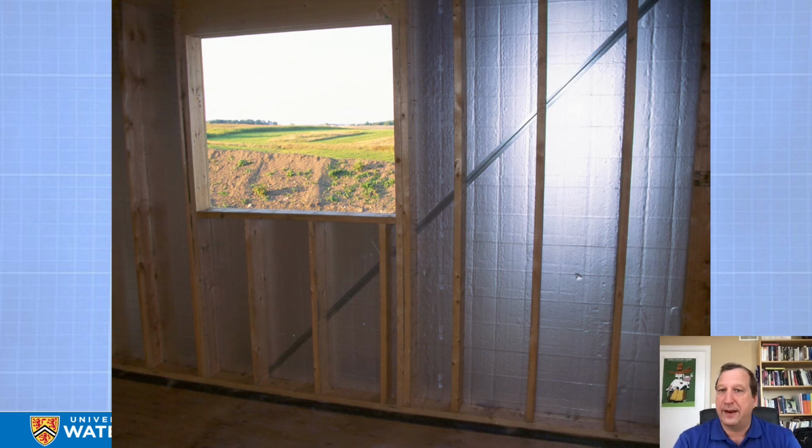This is something that is quite common in low-rise wood frame buildings, to use what's called a let-in brace. By let-in, they cut a slice in the studs, insert a T-shaped piece of metal, and then nail it. And it keeps the building square and does deal with some lateral resistance when you don't have OSB or plywood sheathing to provide that lateral resistance.